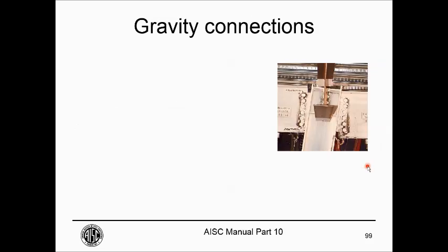This is a single plate connection tested at UC Berkeley out to, I believe, almost or maybe even up to 10% drift. And it performed very well. It's not without damage at that large level of drift, but it's maintaining its integrity. And we wouldn't expect that level of drift demand in our typical designs.